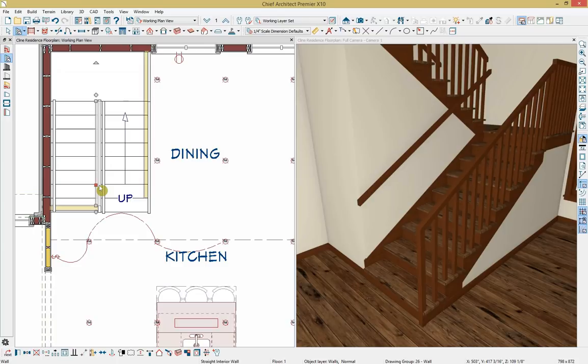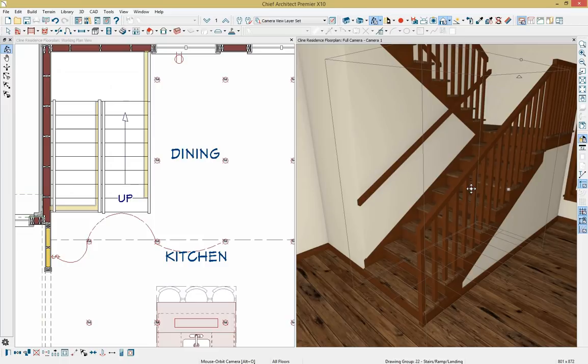So there, those stairs are looking pretty good, and then the last thing I want to do is just remove this handrail against this wall. To do that, I'm going to hold Control on my keyboard and then select this stair section. The reason I held Control was so that I only select one stair section instead of both stair sections at a time. Go down to Open Objects,